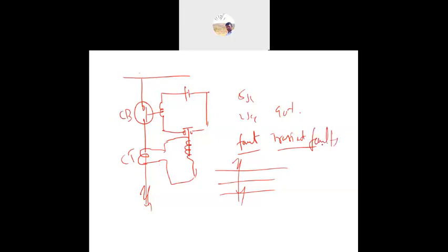Hence, one instant recloser is used for EHV lines. If there is no need for more than one reclose in a transient fault, we use only one recloser. For each EHV line, one recloser in 12 cycles is required. A fast recloser is desired from the stability point of view, that is, if you want stability in the transmission, we require one recloser.